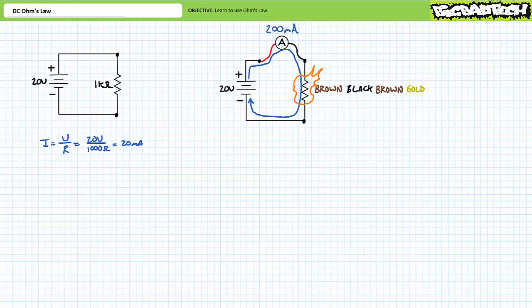Tying this troubleshooting example to the development of good lab practices, had you taken the time to measure the resistance with an ohm meter, or at the very least interpreted the 4-band resistor color code prior to turning on the power, this whole sordid tale would never have happened. Your lab partner isn't just there to make you look good. They're there to dummy check your work. And believe me, you are there to double and triple dummy check their dumb work.